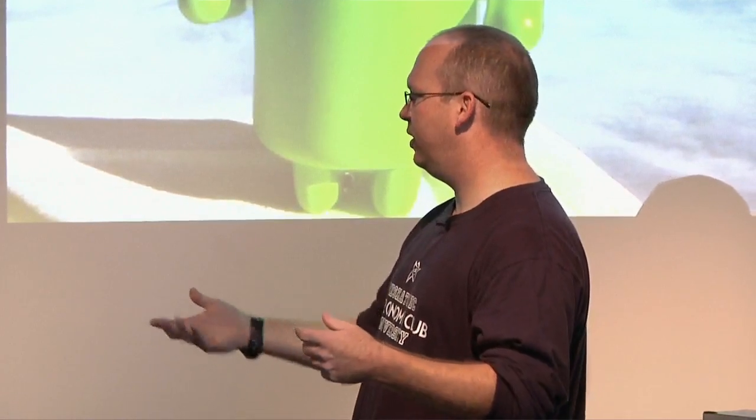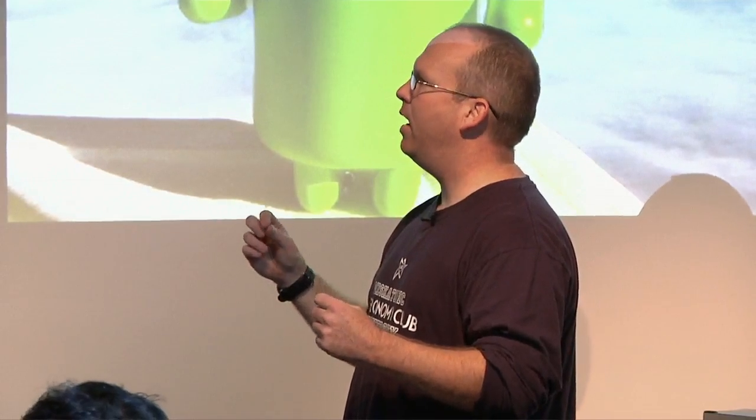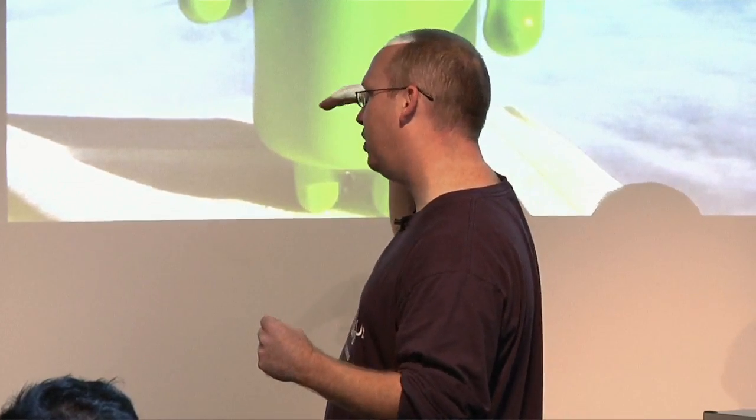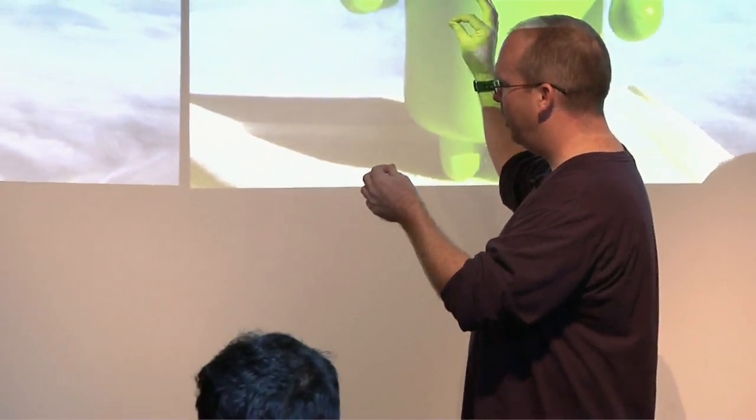So the question is how much of the navigation is handcrafted versus algorithmic. Right now, at least with respect to the control that we're doing with the smartphone itself, it's basically waypoint navigation where we're able to tell it go to this coordinate, turn to this pose. And then it's actually figuring out the thruster mixing that it needs to do to get from point A to point B.